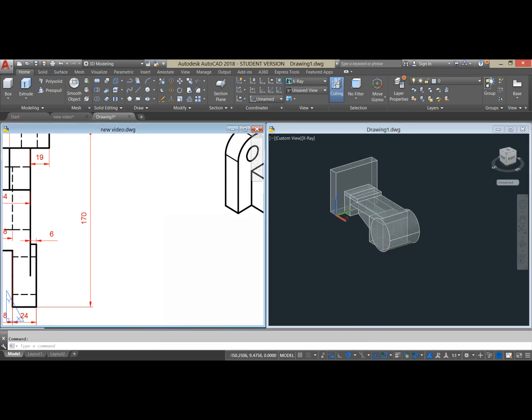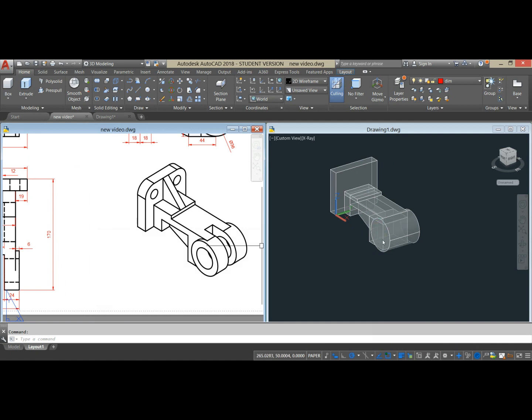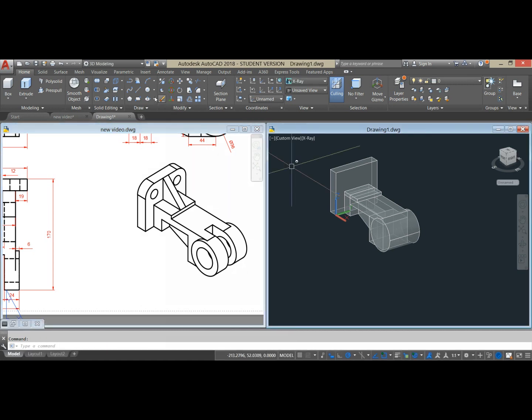Now I'm gonna do a hole at the center, and as you can see here, since we turned on the object snap, I don't have to move the UCS. To make a hole perpendicular to the cylinder, I'm supposed to change the direction of the Z towards that direction. But since this is on, there's a trick here. So select circle from the ribbon and hover over.